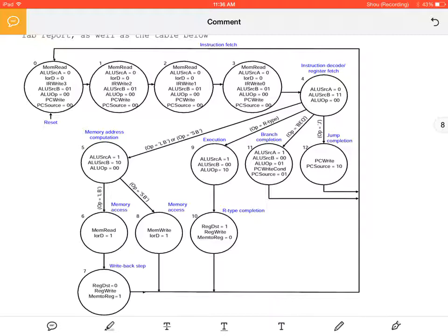So what is the difference between an add and an add-I instruction? Taking an immediate value. Bingo. So is the instruction fetch stage the same? Is the instruction decode stage the same? The execution stage is different. So this here is the execution stage. What's happening is you're just getting a different input value from your add-I instruction as opposed to your R-type.